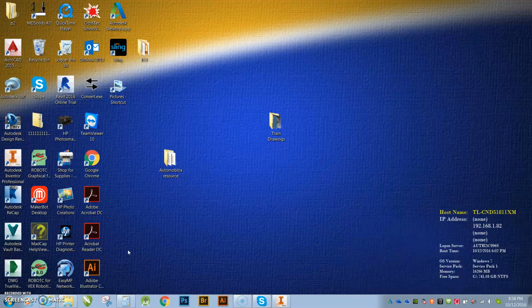Hey guys, so if you're watching this video, we are getting ready to start Inventor using the 3D software. But before we get started actually making parts, I need to go over a few things about the software and the interface. So what I would like you guys to do is, on the desktop, you should see the desktop icon, and it is a capital I, this orange I here, Autodesk Inventor. Double click on that and open up the software.